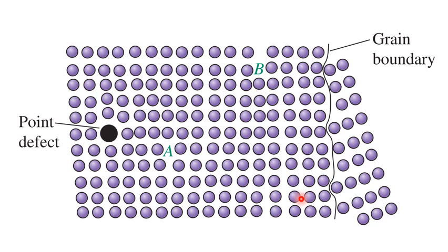When we decrease the grain size, we increase the grain boundary area, and we increase the interference with dislocation movement by the grain boundaries. We can also make the material softer by increasing the grain size. And we can decrease or increase the grain size by what is called heat treatment.